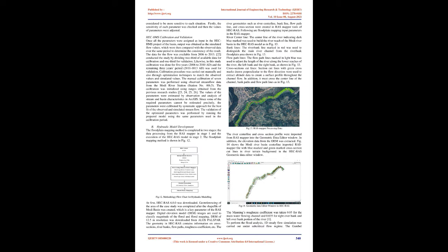Terrain pre-processing using HEC-GeoHMS. For terrain pre-processing, the mosaic DEM clip was loaded to the ArcMap. Terrain pre-processing uses DEM to create a stream network and catchments. Before carrying out terrain pre-processing, the input terrain data DEM was refined using DEM reconditioning. The steps in the terrain pre-processing menu were executed in order, from top to bottom. The steps included were filling sinks, flow direction, flow accumulation, stream definition, stream segmentation, catchment grid delineation, catchment polygon processing, drainage line processing, and adjoint catchment processing.